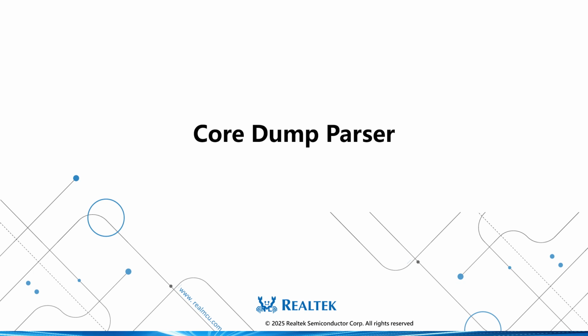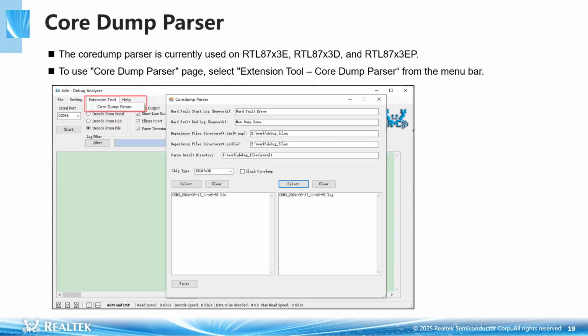Next, I will introduce the usage process of Core Dump Parser in Debug Analyzer. The Core Dump Parser is currently used on RTL87X3E, RTL87X3D, and RTL87X3EP. When an exception occurs, and the CPU register and RAM data dump by log, this tool can be used to analyze the register and memory data, then output the hard fault cause and summarize basic information about the call stack of all tasks, and the basic task information such as task running status, stack state, stack size, usage size, stack watermark information, and TCB address.